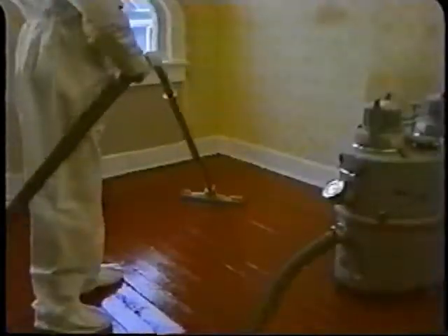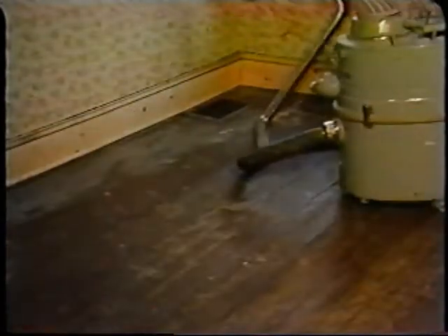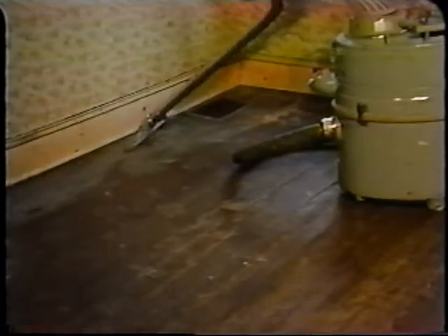Plastic covering doors, windows, cabinets, and appliances should be removed, folded, and disposed of first, followed by the plastic on the floors. After all protective plastic has been carefully removed and disposed of, and all other materials removed from the premises, clean the entire area using a HEPA vacuum, wet wash, HEPA cycle. First, the entire work area should be thoroughly HEPA vacuumed, starting with the ceiling and working down to the floor.